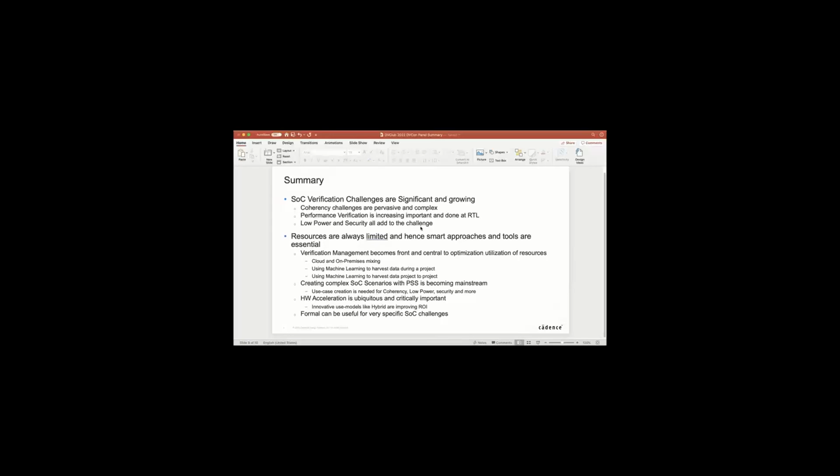So the only real way of doing that is to do full-blown chiplet-to-chiplet modeling. Now what you can do is build a partial model of the chiplet with just the IP that is involved in that coherent path. But that's extra work. Obviously, you need to plan that and say, I'm going to do a partial build and black box lots of other pieces of the chiplet in order to make it, firstly, run faster, but also not use huge amounts of hardware capacity.